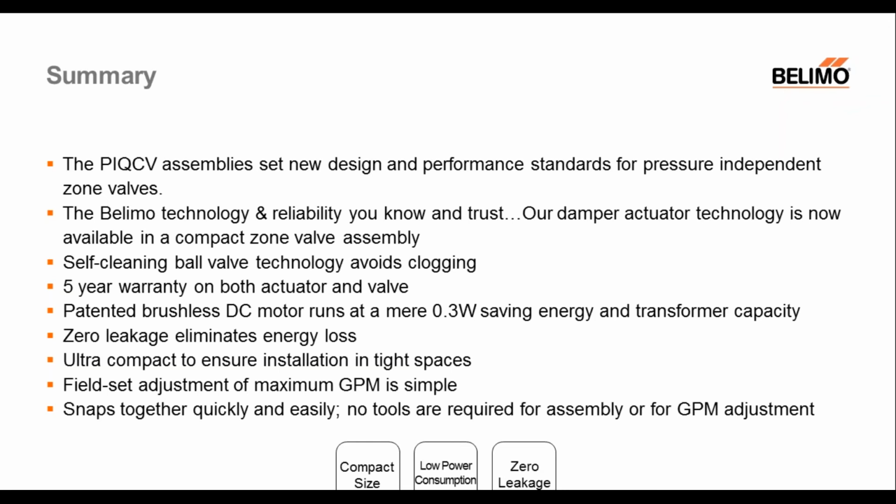The PIQCV, because it's built on a ball valve technology, it's self-cleaning. So as it opens and closes, it's cleaning itself. It's built on the Belimo technology and reliability that you know and trust, or damper actuator technology that you've known over the years is now available in a compact zone valve actuator.